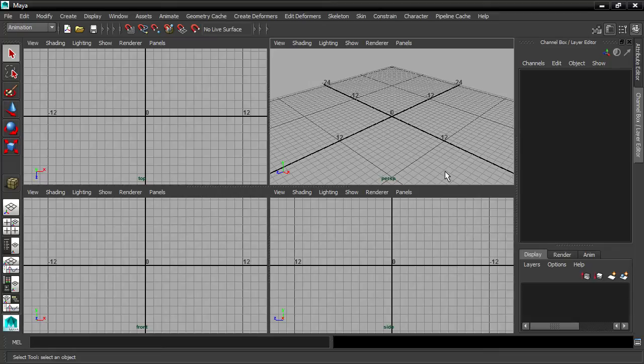Just as with any images in Maya, or really in any 3D program, you need to place the image into the appropriate folder before you create the object or material. This is super important, and I cannot stress this enough. Before you create an image plane or a material texture, you have to find your image and then place it into the appropriate folder inside the current project. And once it's inside there, then it's okay for you to create the image plane or texture and link to the file inside your current project.